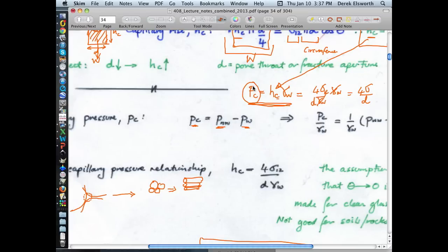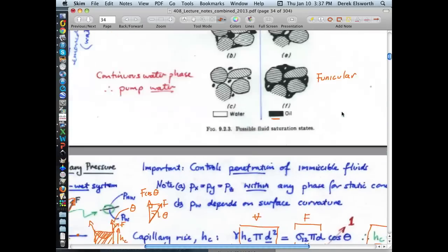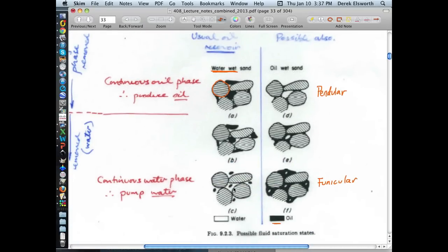If it's a lone bead, a marble if you like, within the straw, then for any given interfacial tension between the water and the oil, which is kind of set, if the diameter of this is very small, you have to apply a very big pressure to be able to get it out. If you can only apply a pressure which is due to flowing fluid, which is not very large, then you're physically just not going to be able to move it out.